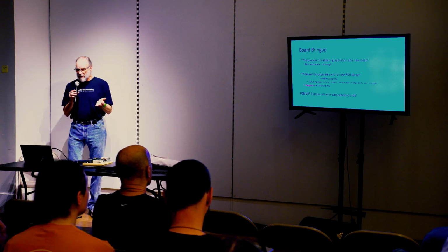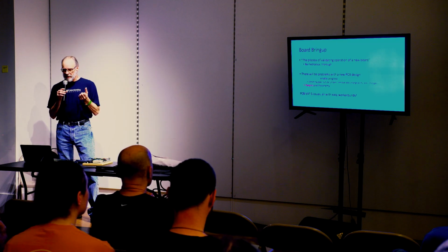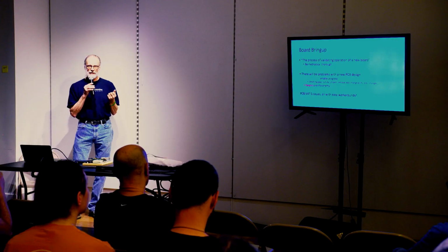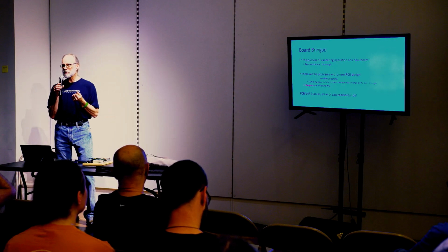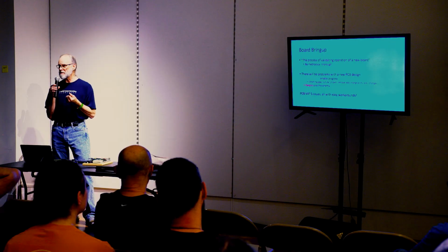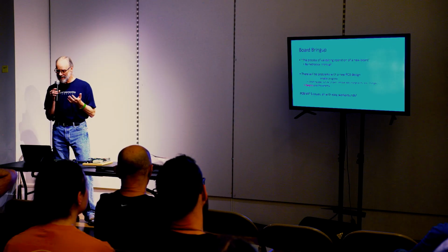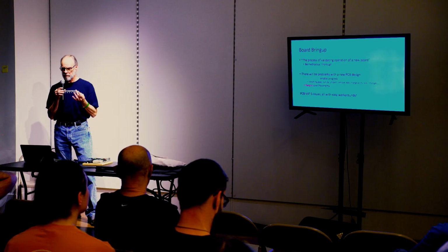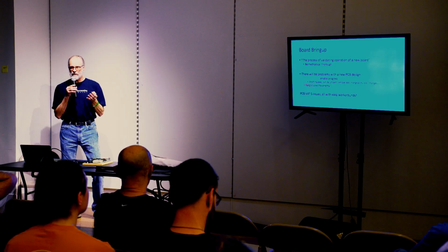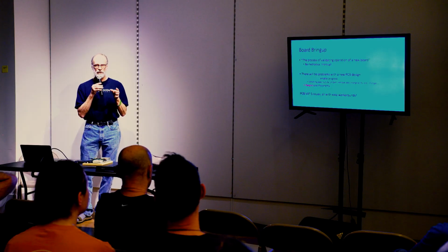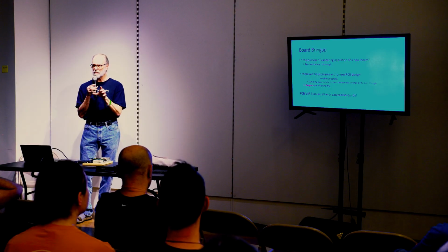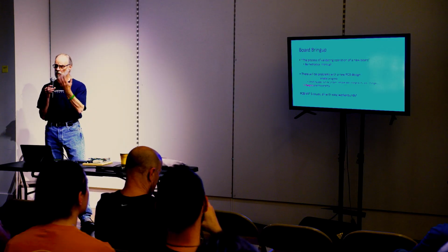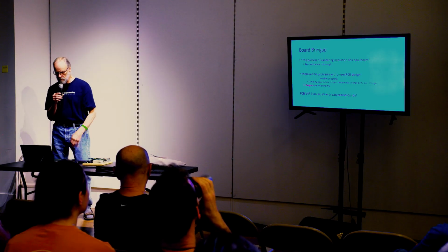So once you get a board back, you bring it up, and it is the process of validating operation. It's tough because you have to walk before you run, but of course you just want to run. You have to be methodical, you have to be thorough. There will be problems. Workarounds are the key. Anything that you can do to not have to respin that board, you do. Because if you have to respin it, it's time and money waiting for it to come back again.